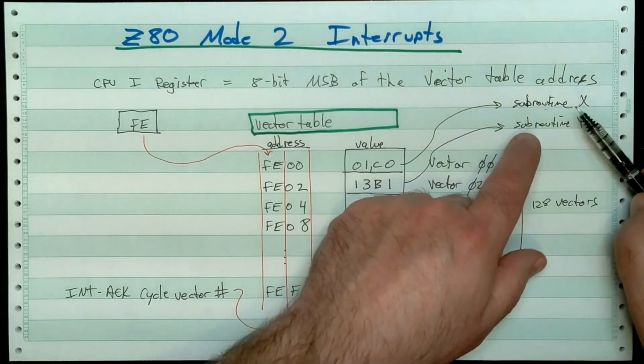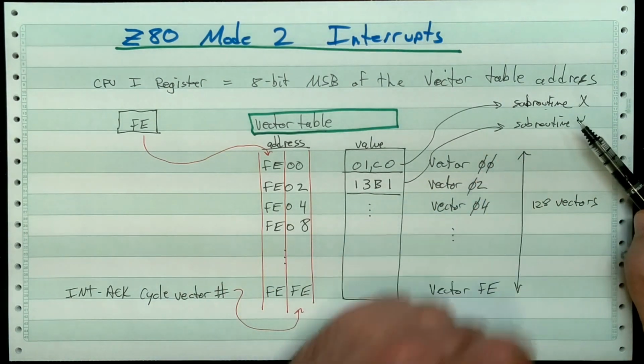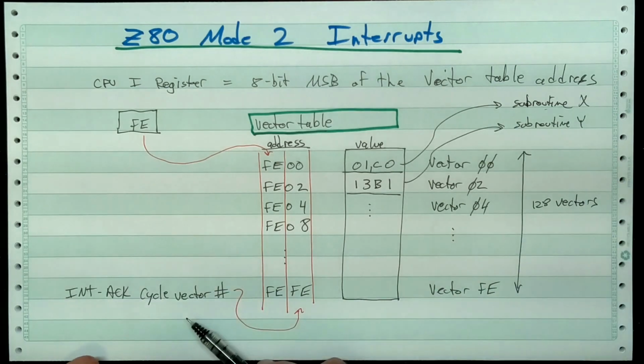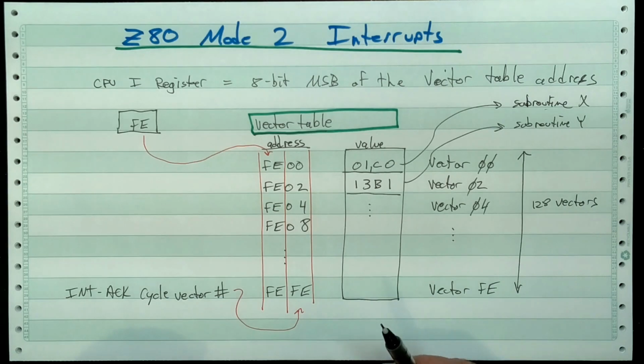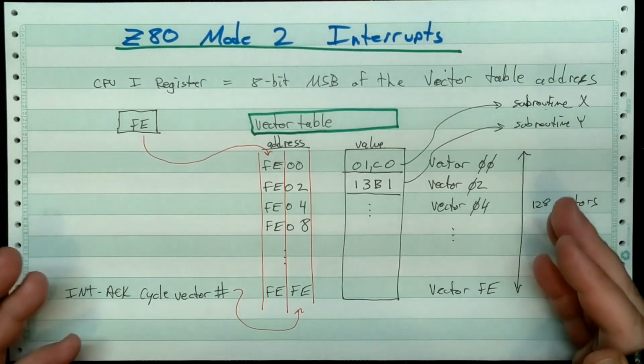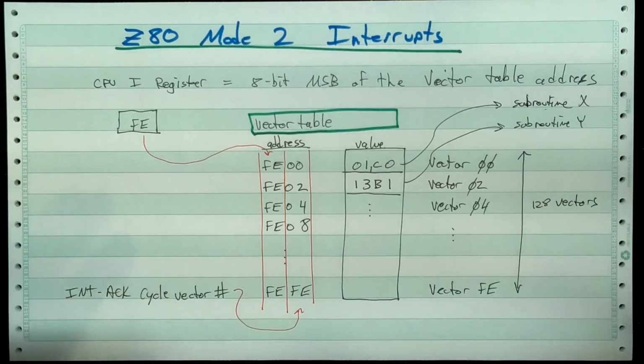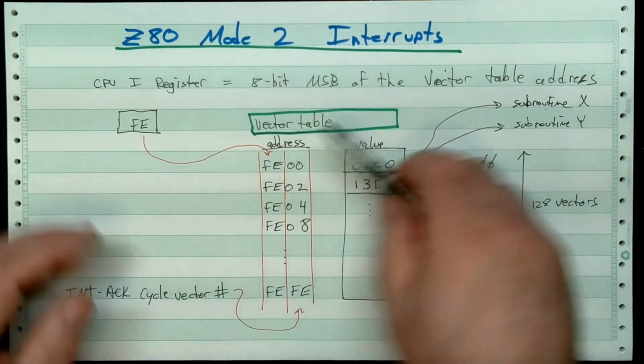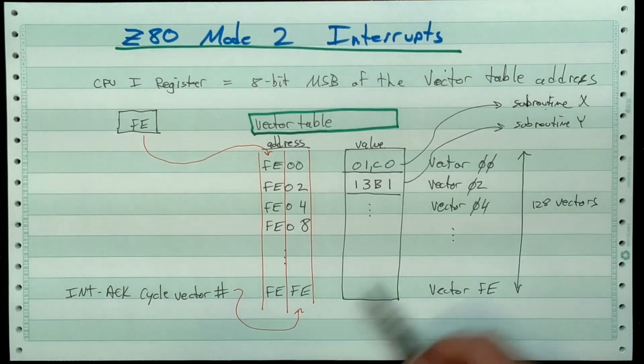These subroutines we refer to as interrupt handlers, because they're called through this vector table to handle the receipt of an interrupt signal. So this is the basic thing we have to create and configure so that we can then tell the Z80 to handle the interrupts, and then it'll use the lookup table here to figure out where to go.